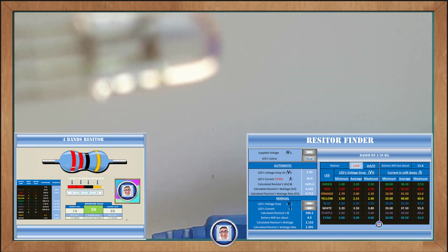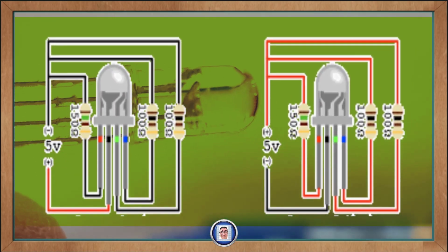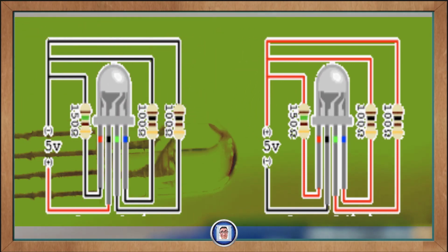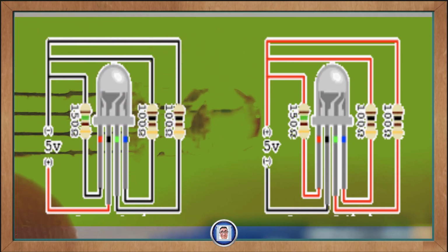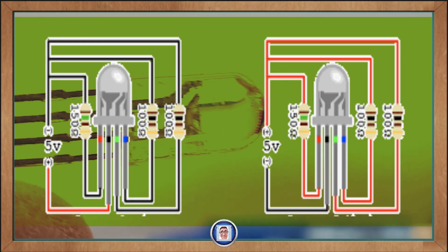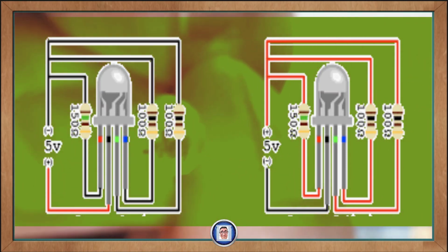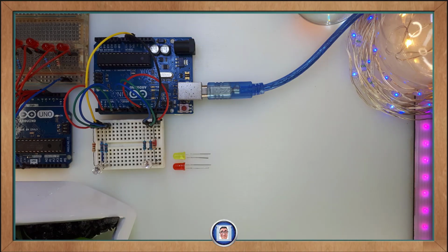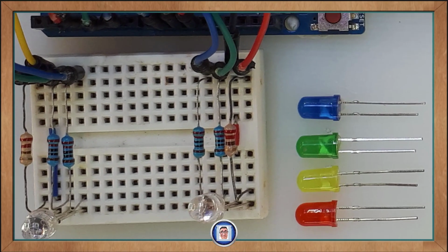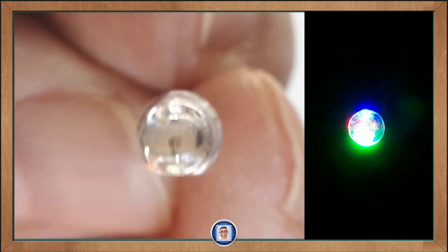Over here, this is how the 2 RGBs are connected. You notice that normally the red LED needs a bigger resistor than the rest, and this is due to its voltage drop being lower than the 2 others. The other option we have, and that's the one we will use, is to use a bigger resistor for all. That's why we will use 220 ohms for the demonstration. With this, the LED might be dimmer, but in the long run, this will preserve them. And this is good to know.